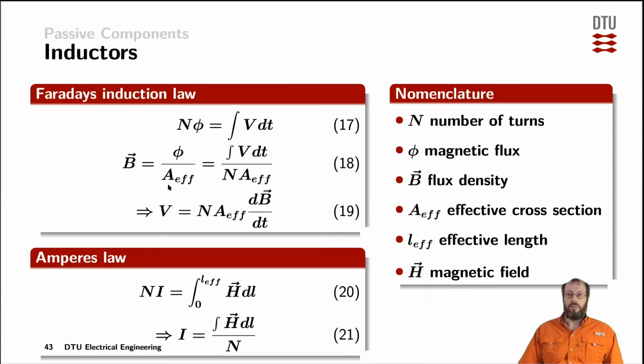Now, looking at the physical laws behind the inductor, we have Faraday's induction law and we have Ampere's law. Both of them are built on Ørsted's discovery of electromagnetism. Faraday's induction law tells us that the number of turns times the magnetic flux is equal to the integral of the voltage over time of that inductor.